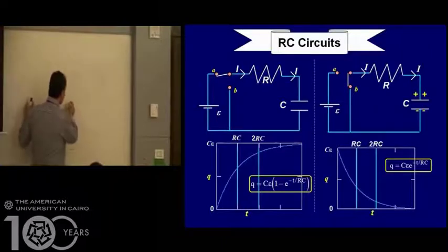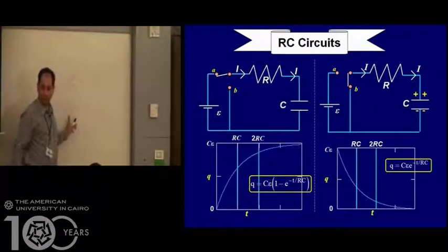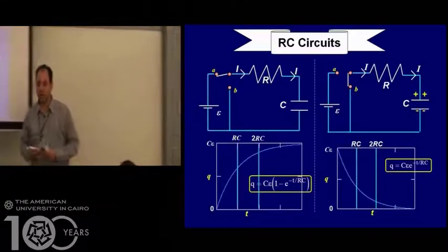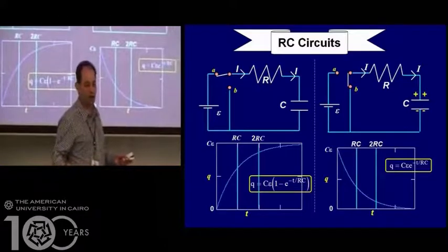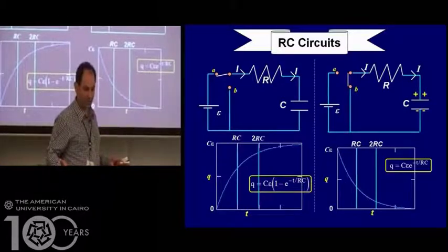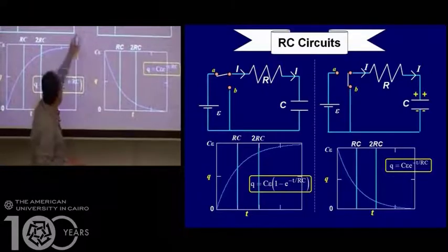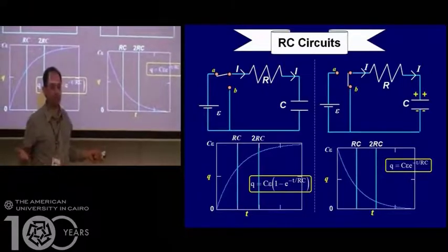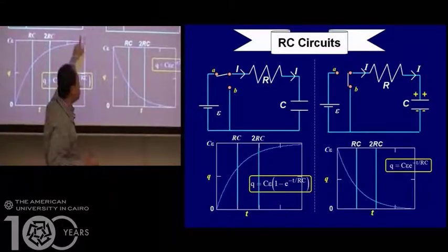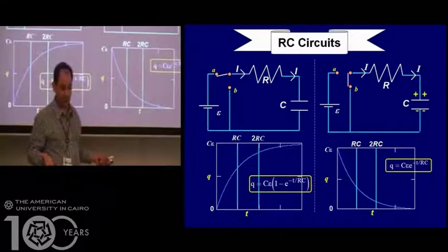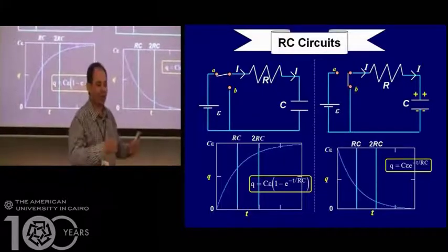Okay? So Q equals CV. If Q is 0, that means the potential difference across the capacitor is 0, because the capacitance is only a function of the geometry. So the charge is 0. If the charge is 0, we call those two plates an equipotential surface, because the potential difference across them is 0. So those will act like just a wire to us.